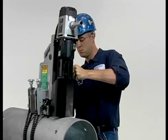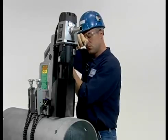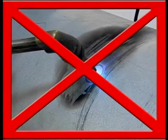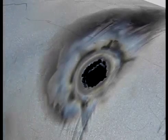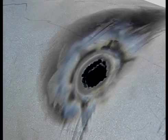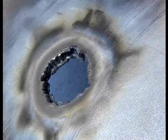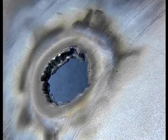Always make the hole to the specified size using a drill bit or hole saw. Never ever use a torch to cut this hole. Torch cutting creates pipe burrs that will disturb the flow and cause measurement inaccuracies. It is also very difficult to precisely control the hole size with a torch.